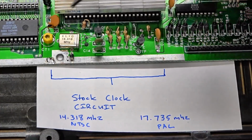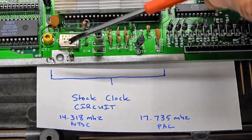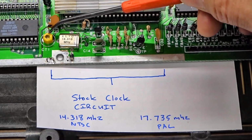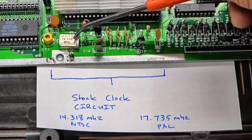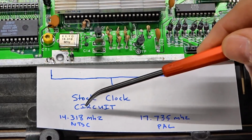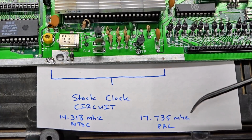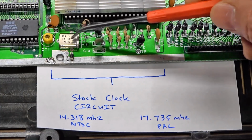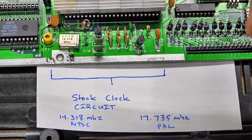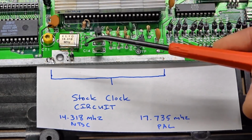Since this is an NTSC machine, this clock generator here has a 14.31 MHz crystal. This little yellow variable capacitor here is the trimmer that allows you just to home in on exactly the right frequency. 14.318 MHz for NTSC and around 17.735 MHz for PAL. So if I did swap out this crystal oscillator, I could make this machine a permanent PAL machine, but I really wanted to be able to switch between the two modes.